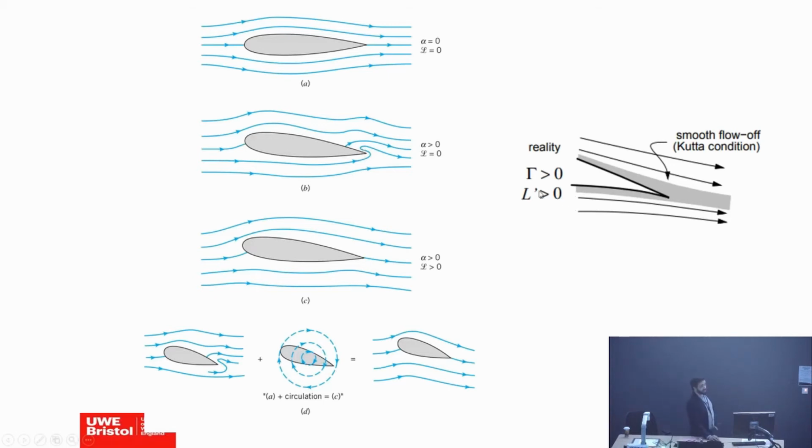So, what the Kutta condition said, Mr. Kutta, I think he's a German mathematician, Martin Kutta. So he said that to fix the value of circulation and therefore to fix the value of lift, the flow at the trailing edge must leave smoothly. So when you think about it, okay, what do you guys think about the flow leaving at the trailing edge smoothly? In terms of velocities, what do you think that point is? If something is leaving smoothly, what do you think the speed is there?